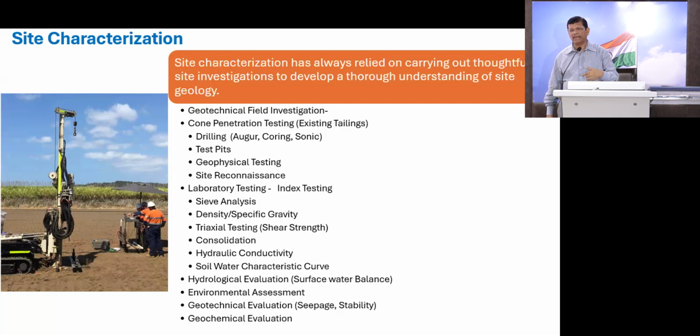And right now in most of the projects I have worked on, I always recommend using a sonic rig, doing the sampling using the sonic method, so that we can easily see those samples, what exactly they are, subsurface, coming from the tailings.